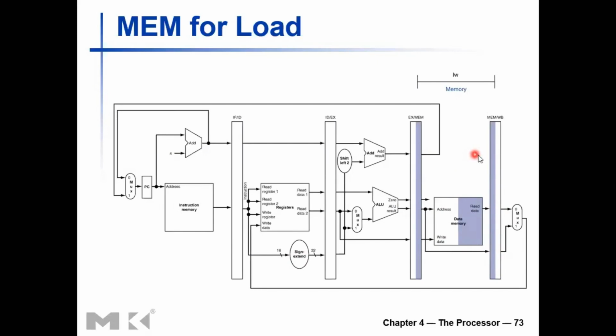So at the end of that clock cycle, we need the data read from the data memory to be ready in this line, this set of lines, a 32-bit value, a 32-bit result from the ALU, which might need to be written into the register file in the case of arithmetic logic shifting type instruction. And any relevant control signals should be preserved or saved in this register file. All those values should be available at this point at the end of the clock cycle, right? So the dominating piece of equipment here is the data memory. It will consume the most time within that clock cycle.